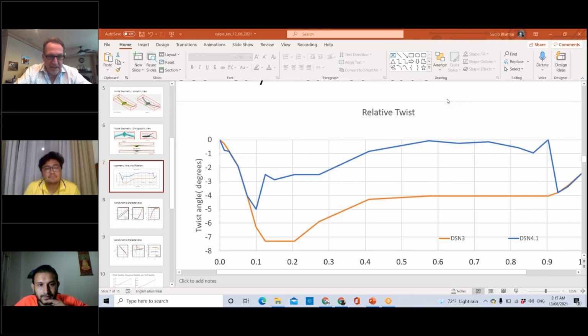But you've also got some handling information, finding out the issue with the far aft gear. So yeah, if we do a half and half, bring that winglet forward a bit, put the gear aft a little further than directly below the wingtip, see if we can keep that gear fixed to the wingtip. And if you say, hey, this is okay, I can manage this, then that's a good start. And then we can think about other things related to maybe what some people do.